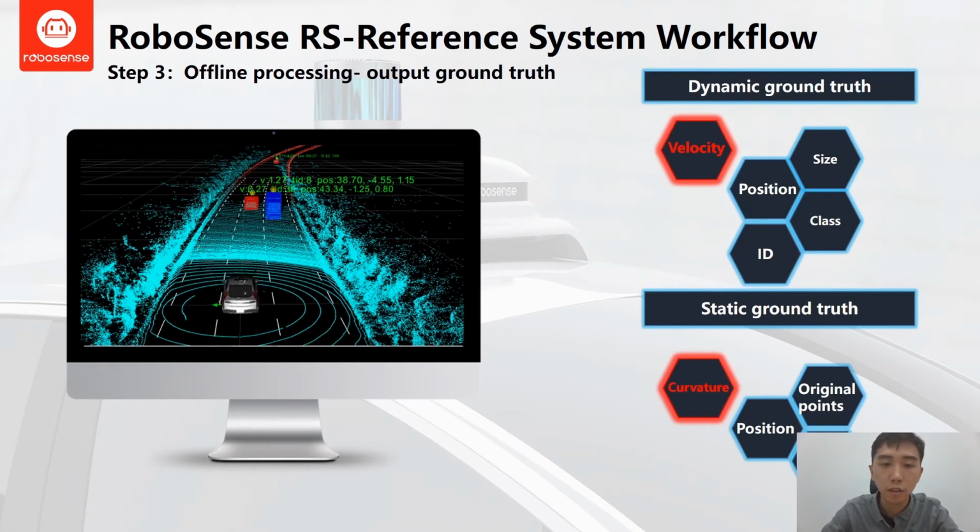Okay, here shows an example of the processed result. Here you can see the original point cloud. We can see the lane line, these white lines, and the road curves, and some moving targets. For the dynamic ground truth, we can generate the velocity, position, size, class, and ID of the targets. And for the static ground truth, we will generate the curvature, position of all these lane line and the road curves.